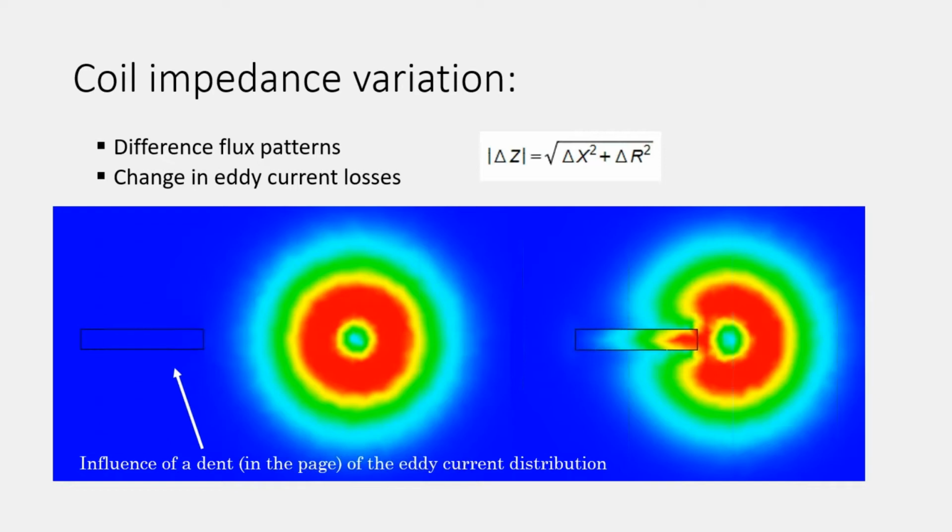At the same time, those eddy currents will generate a magnetic field, which for different positions of the probe can be different, and in turn will affect the initial field produced by the probe in different ways, which will be reflected through a different equivalent inductance of the probe.